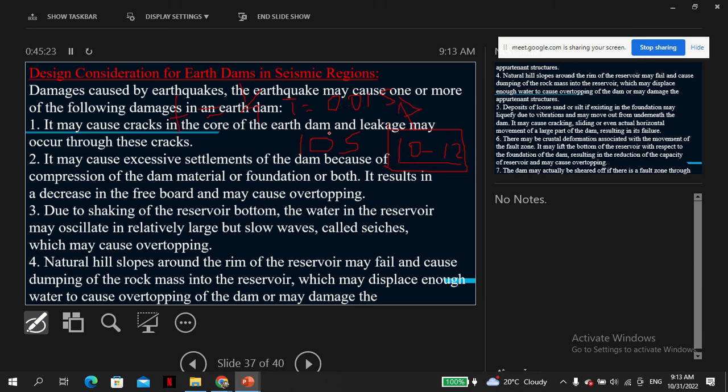Quite practical. So they realize, in fact, that other buildings are just safe. 8 and below are just safe. 15 and above are safe. But these buildings get severe. The reason is the natural frequency of the earthquake and the natural frequency of the building, especially at that height. You said you did not study earthquake, but if you did, each building's height has something to do with its frequency, of course.